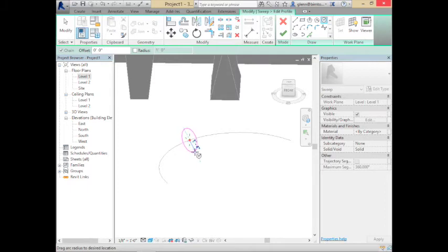I'm going to pull a circle out. That circle is now basically going to follow that path. So assume it's the circle and that red dot's going to follow that path. So when this gets done, what's it going to create? Yeah, it's kind of like half of a hula hoop. Yeah, it could be a handrail. It could be all sorts of things like that. In fact, when we do railings and they have that curved handrail, that's how it's made. It's made as a sweep.